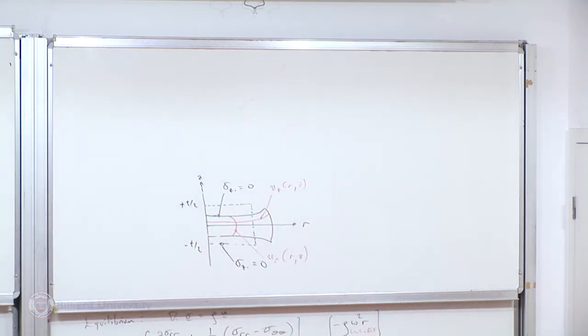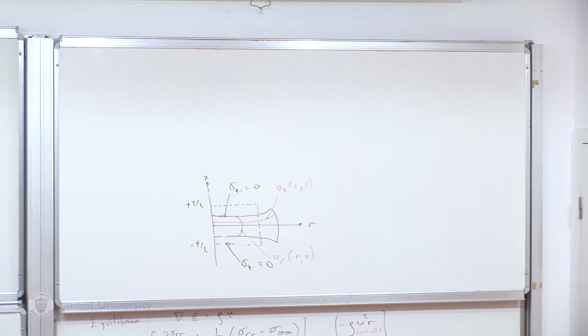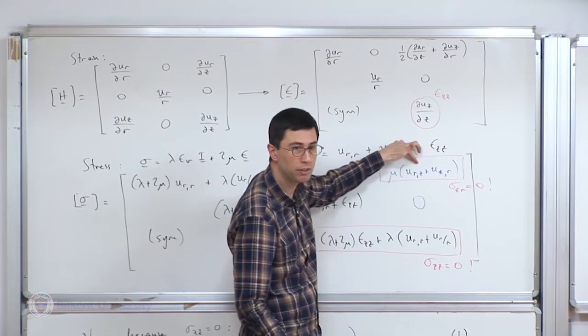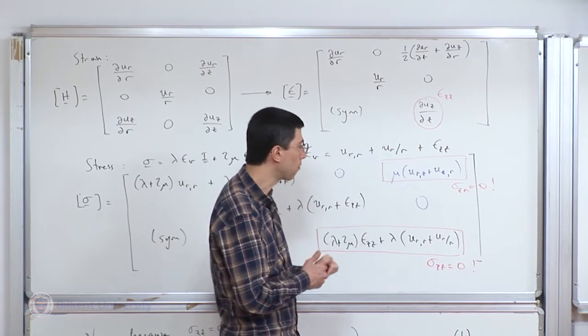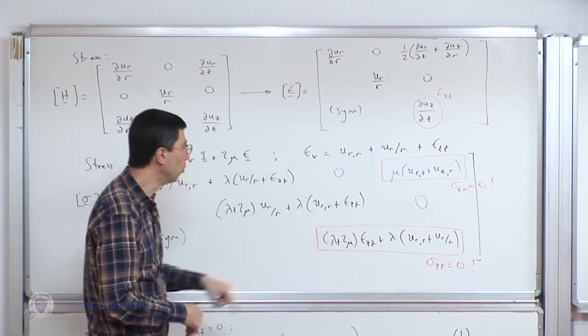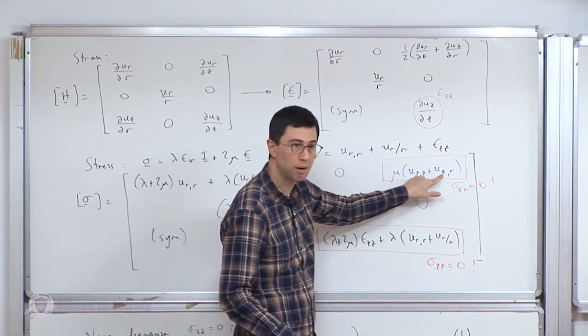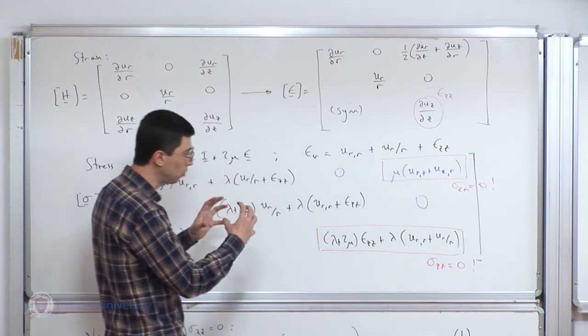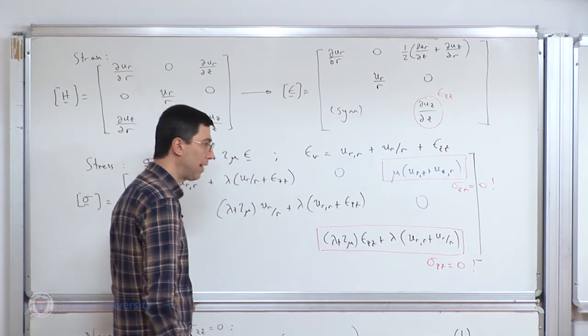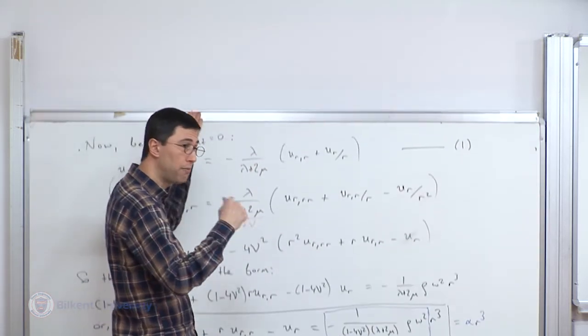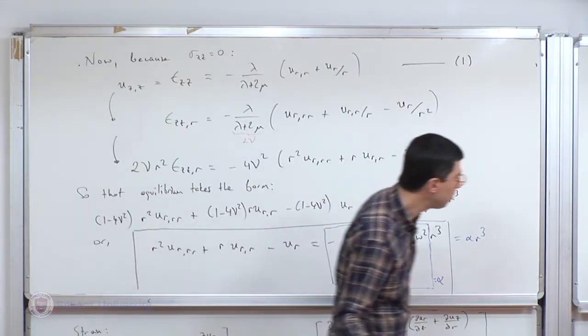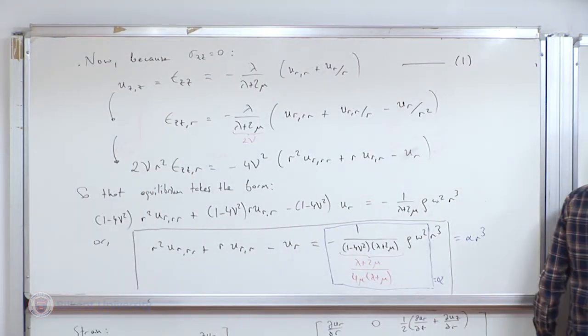And the motivation is that there's certainly a variation, and it turns out that I cannot quite omit it. Why can't I omit it? I hate going back and forth, but I want to highlight, right? This is 0. This and that individually, they're not necessarily 0. In fact, they're of comparable magnitude to UR comma R and UZ comma Z. So I cannot omit that, but together they are 0. On the other hand, the absolute variations of the variables, not the gradient, I'm going to eliminate that dependence by doing averaging over the thickness.